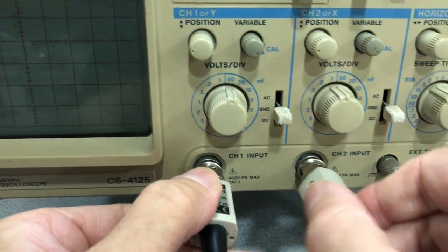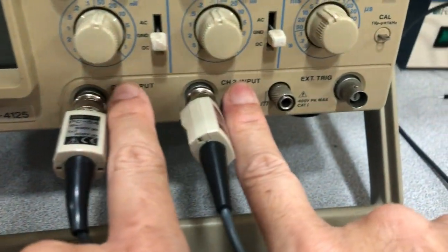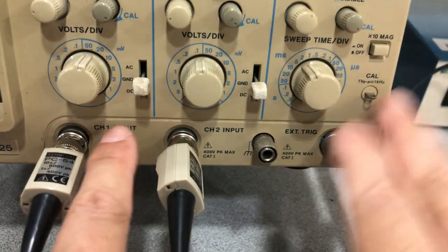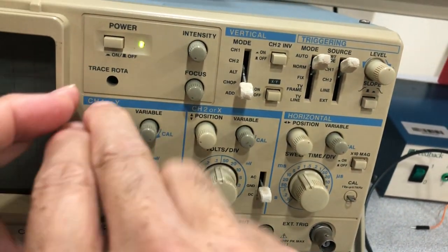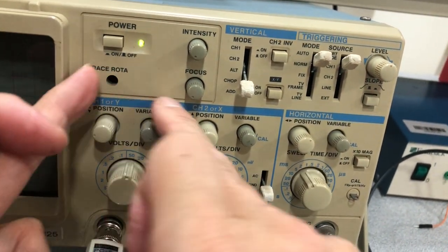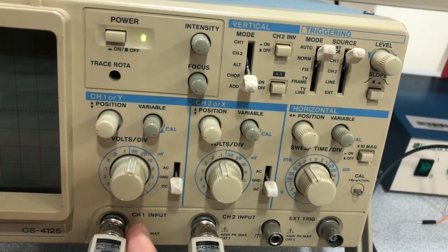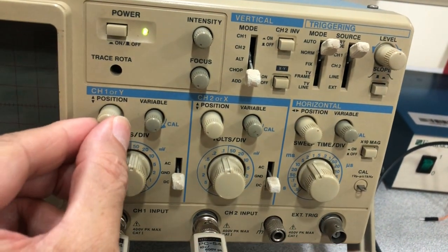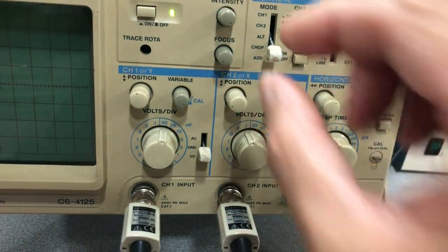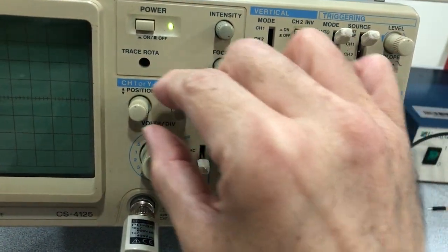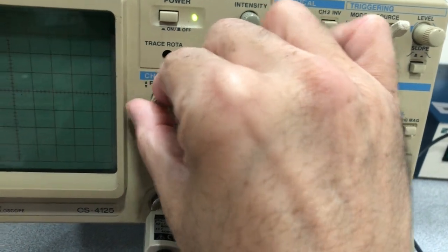I have 2 channels in this scope. Channel 1 input and channel 2 input. There are more advanced features I'm not going to talk about today. Let's learn the basics. So channel 1 input has these channel 1 controls, okay? We'll talk about them. Let's play with the intensity, take it to the max, and then you have to move this position, okay?